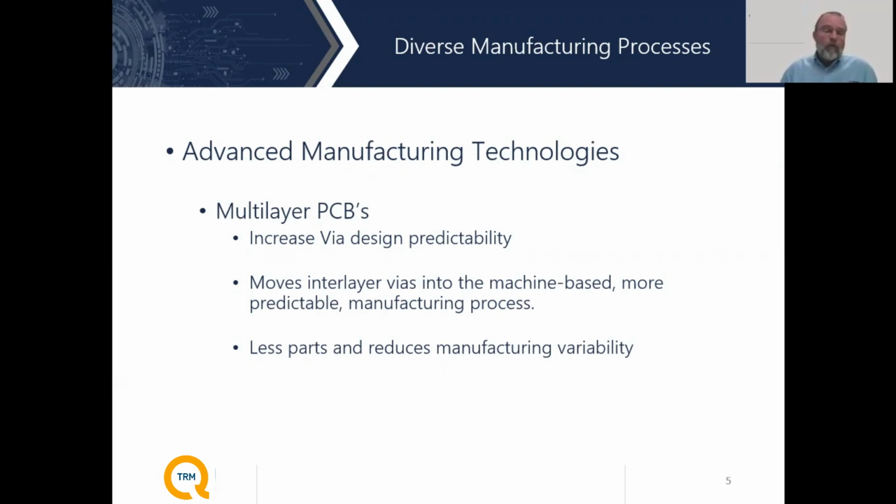The other thing that you get when you move into a multi-layer PCB is that it allows you now to build components that utilize this sort of construction technique of going into a bonded strip line type of technology that can be used for surface mount components. Therefore, you can not have a housing at all and still have a robust mechanical package.